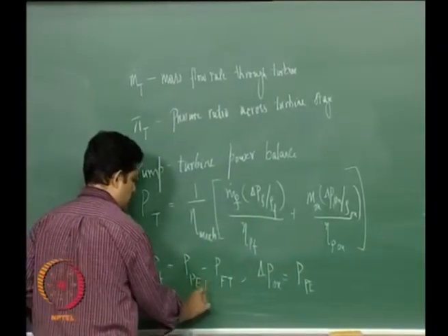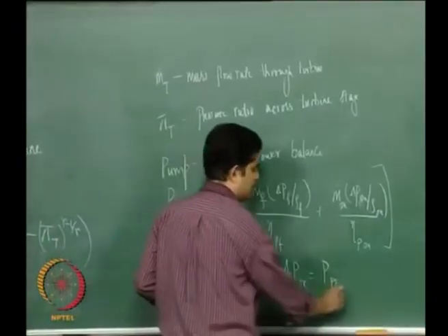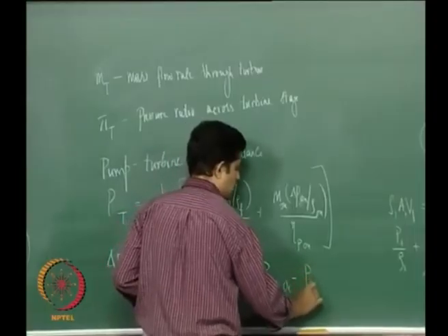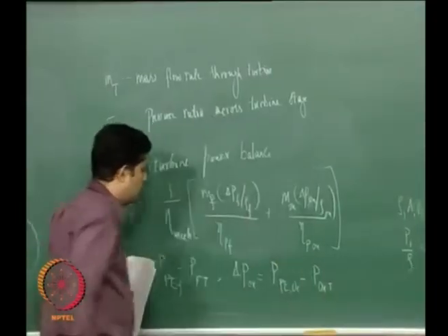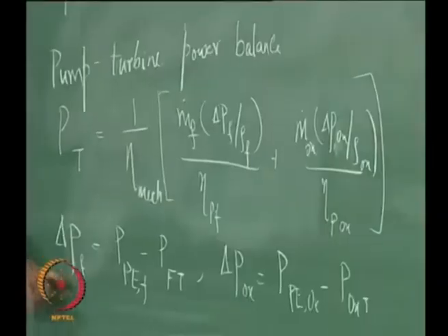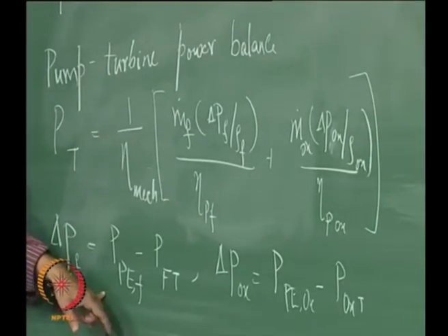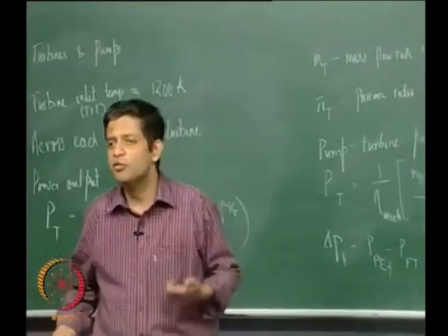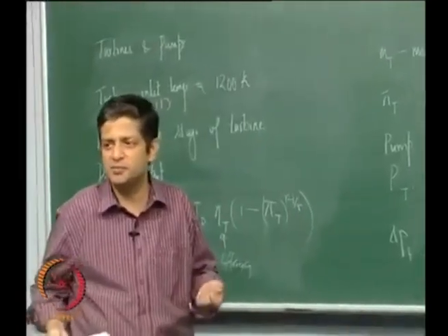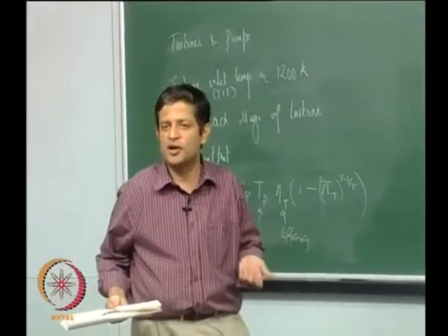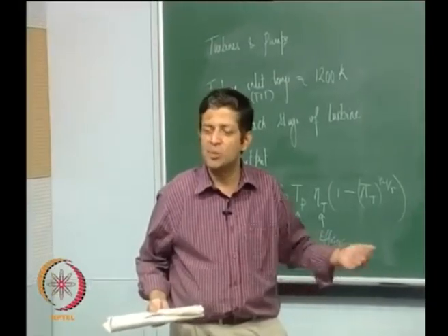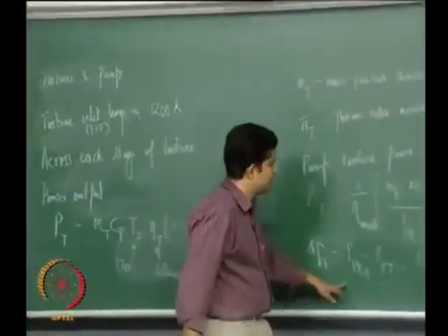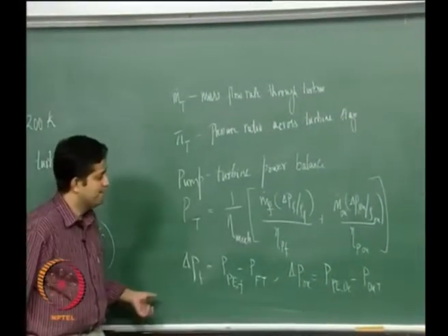let me put a fuel subscript here and an oxidizer subscript here. Simply because the exit pressure of fuel and oxidizer need not be the same, especially if you are only going to take one fluid through the regenerative chambers, right. You are only going to use one of the fluids for regenerative cooling, that one will have to have a higher pump exit pressure. So, these two are not the same, okay.